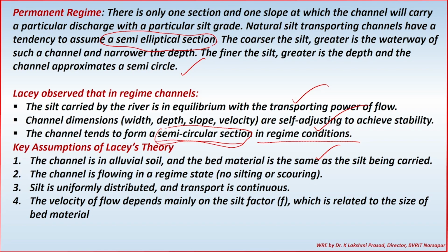So that's why the channel you are now designing is also in alluvial soil. The channel is flowing in a regime state, that means no silting, no scouring in the channel. And silt is uniformly distributed, and transport of that silt is a continuous process.